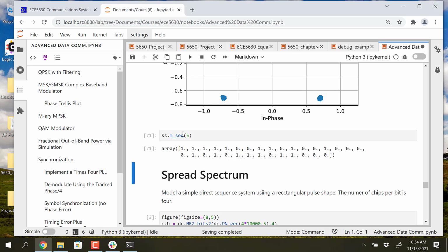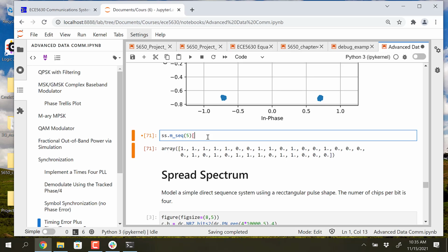And I've had people from other places say that's not the real PN sequence. This is just an interesting comment. First off, you can see my generators start off with that pattern of n 1s, and then if you look through it, you'll see an occurrence of 3 1s. I thought there was an occurrence of 4 1s in here, but I don't see it. But this person I used to work with at Cosmic said your PN generator's not correct. Well, there's no exact right PN code. This is a 5-bit code, but it can be flipped over. It could start in a different spot in the pattern, but you've got those two options. You can run it forwards or backwards. Also, you can XOR them with data to get more bit transitions, right?